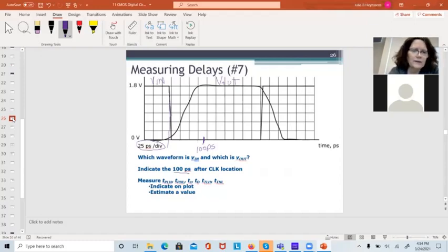And then each one of these, if I told you there were 1, 2, 3, 4, 5, 6, there's 0.3 volts per division. That means that each one of these squares is 0.3 volts. And we could measure those on here, but there is no way I can draw this on the screen.